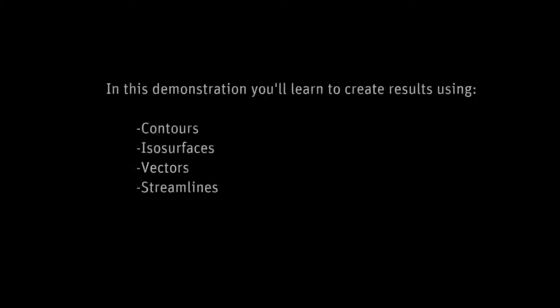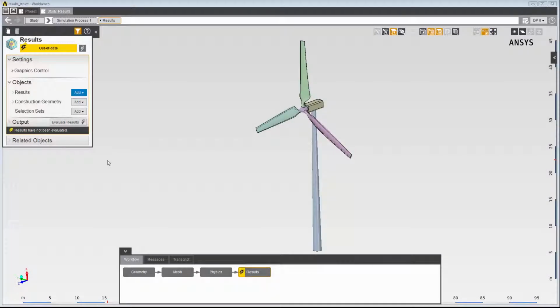In this demonstration, you'll learn to create results objects in ANSYS AIM. You can create contours, isosurfaces, vectors, and streamlines to process numerical and graphical visualizations of your simulation physics. I'll use a wind turbine geometry to create results objects to visualize the interaction between the air and the wind turbine. For the solved structural simulation, I'll start by adding a predefined contour result to visualize the equivalent stress on the wind turbine due to the force of the wind acting on the blades.